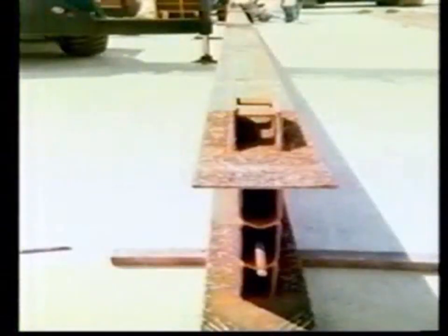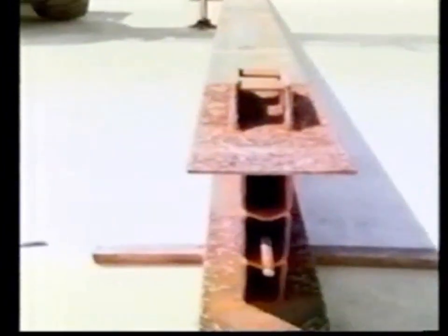A disposable shoe protects the opening during the probe driving step. The center rod seen is retracted during emplacement and pushes the shoe off pneumatically. The walls between the channel iron have cut-out sections to allow iron to flow to each of the chambers to equalize the distribution of iron in the probe. These cutouts extend for about 12 feet up into the mandrel. The rod is in a protective casing to minimize bowing.